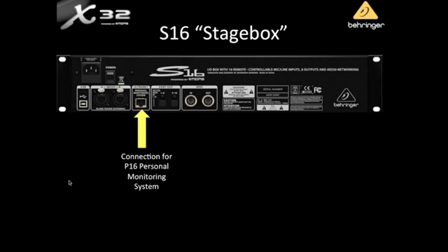And what's really cool is this runs down that same cable as your AES-50, so you're not running a separate cable from front of house. You plug in your AES-50, and then those 16 channels come out of that Ultranet port. This is one of those things that puts a smile on a lot of engineers' faces when they realize that they can give different musicians, say in a stage environment, you have a drummer or a lead singer with in-ear monitors, you could add a P16M personal mixer station right to their mic stand, and they could adjust what's feeding their in-ear monitor mixes individually for each of those 16 sources, create their own custom mix.